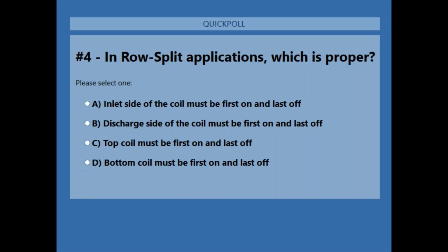Now, you want to be careful on some of the ductless split systems because their liquid line actually isn't even a liquid line. It's a multi-phase or tri-phase line. But with standard DX commercial, no, we don't insulate the liquid line. With one caveat to that.